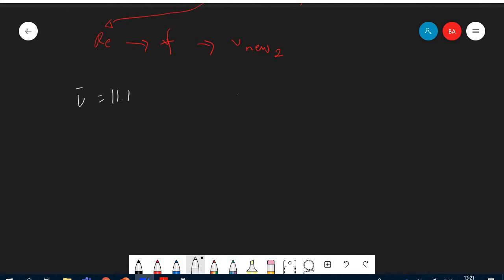So that will be something like a Fanning friction factor of 0.003, right, 11.1, and then you're going to calculate the Reynolds number. You can do it the other way around, by the way, okay? You can assume an f number, just any f, and then by putting an f term,